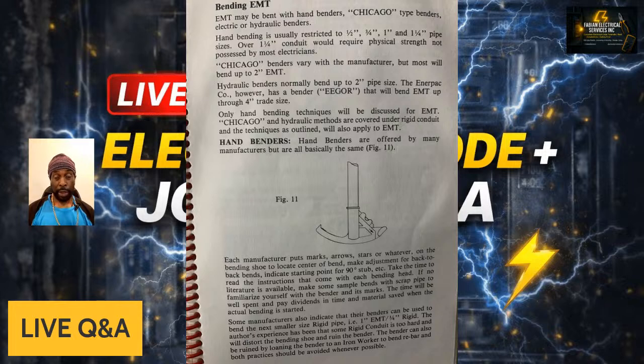And again, as you go on, once you're bending conduit, you will see that your conduit will start to get older, and it will lose the paint on it and so on. And with some benders, if you don't know what you're doing, the bender might be damaged, and when you start to bend pipe, no matter what you do, the pipe will kink and so on. So you have to take that into effect.